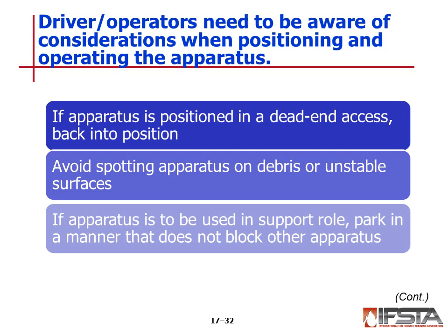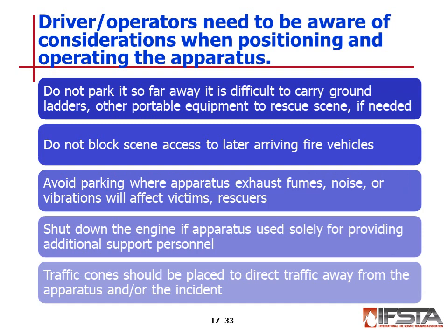Avoid spotting apparatus in a location that will require the apparatus to be stabilized on top of debris or otherwise unstable surfaces. Park apparatus in a manner that does not block other apparatus that need to be closer to work in the area. Do not park so far away it is difficult to carry ground ladders and other portable equipment to the rescue scene if necessary. Do not block the scene's access to late arriving fire vehicles.